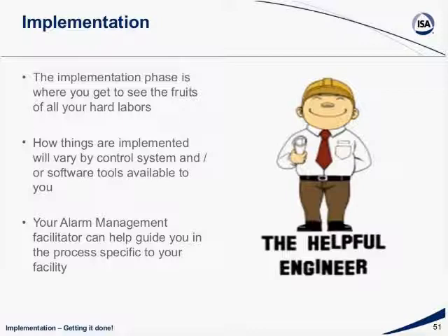Talk about the implementation, okay? This is where you see the fruits of your hard labors, okay? How things are implemented will vary based on your control system and or the software tools you have available to you. Really talk to your alarm management facilitator. They can help guide you in the process specific to your facility. If you have the right tools in place, the implementation becomes very easy in that you update the master alarm database, and then the changes are propagated to the control systems automatically. Otherwise, it does become a bit of a manual effort, and that's not a lot of fun, not the glamour side of the job. So having tools available is really important.